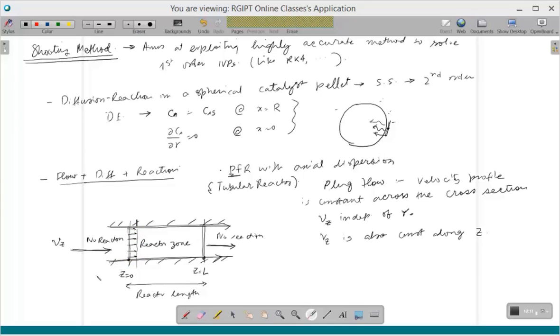Boundary layers do become important when you want to calculate some quantities, for example stresses acting on the surface, or heat transfer. But in our problem, boundary layers are unimportant, so we ignore that part, and largely we'll assume that the flow velocity is constant. So that's plug flow.